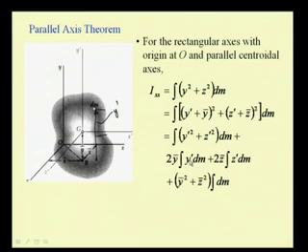What are these two quantities? That is integral y prime dm. It is nothing but the first moment of the mass with respect to a centroidal coordinate. So, this term becomes 0, because it is possible to find a mass element which has a negative y value corresponding to this mass, and so this integral becomes 0, as well as this integral, integral z prime dm, also becomes 0. So, we are left with these two terms.